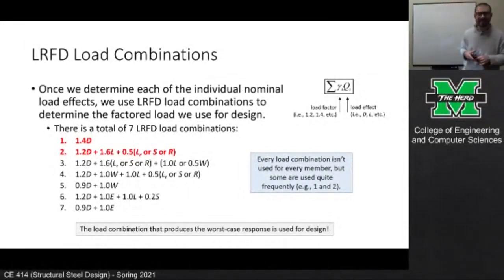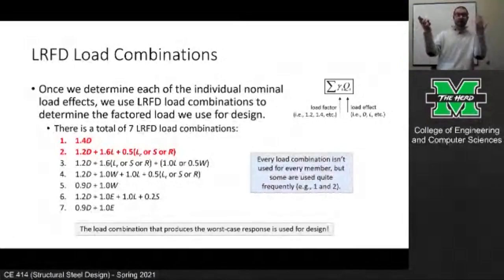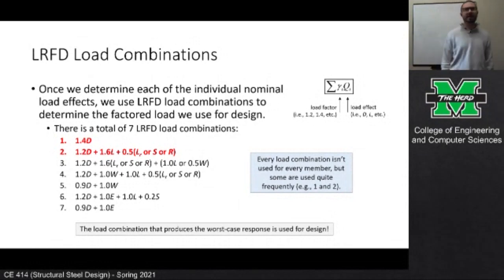As I was saying, there are some loads that you're not going to see reflected. Like for instance, R. R is the rain load, and with adequate drainage, you can neglect rain loads because the snow loads that accumulate and stay on the roof will tend to be heavier anyways because they're permanent and stationary. The other, L sub R, is the live load on the roof.